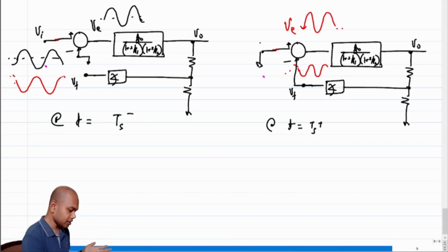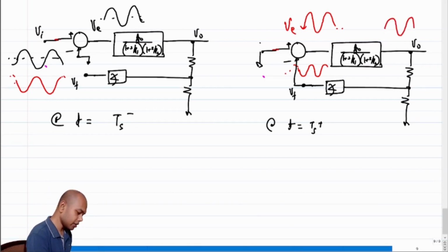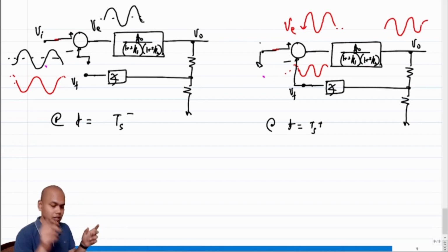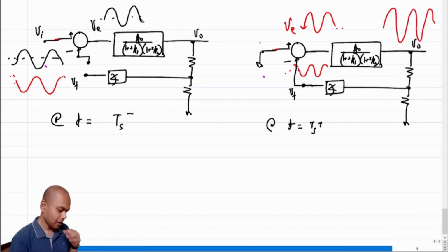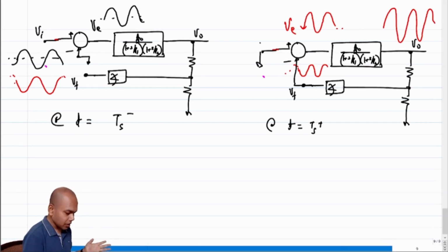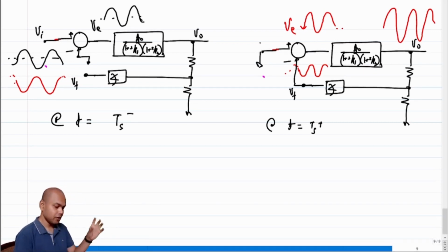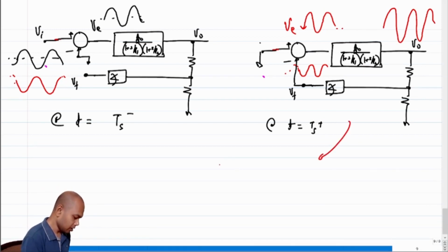So what would have been the output? In this case, output is basically the inverted version of the input, right? Because amplitude is, in this case, k times amplitude and inverted in phase, right? So this, when seeps through to Vf, gets reduced in amplitude by a factor of k and becomes again equal to the amplitude of the proverbial input, which means that this becomes a self-sustaining loop, right? So this will be a self-sustaining loop or an oscillator.